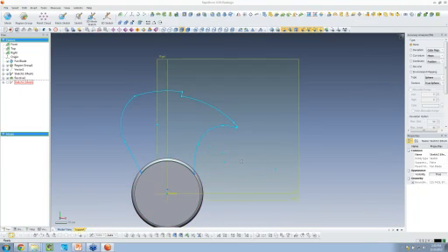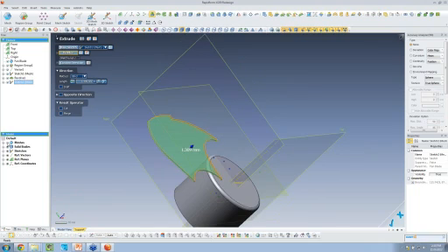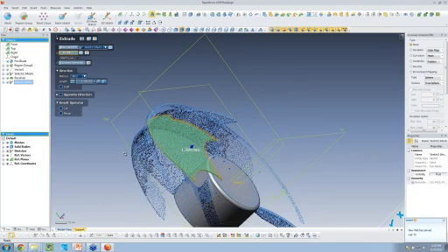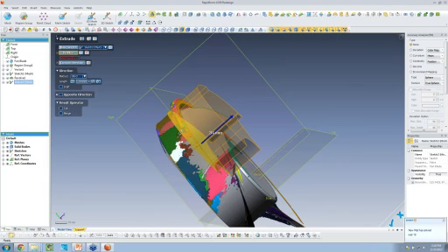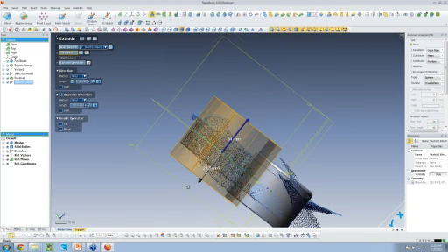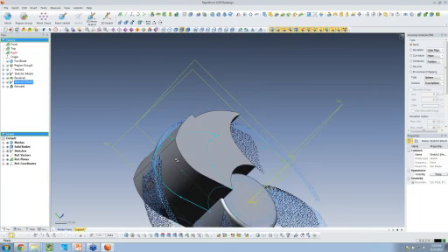I can use that profile, and what I'd like to do is build an extrusion from that. So let's see what we have. Let's make sure we have enough. So I'm going to extrude that up, but I don't have anything on the bottom, so I can also extrude down. Okay. And with those extrusions, when I come back, I'm not going to merge it to my first feature, so I got my merge tab off. So there's a nice profile of my part.